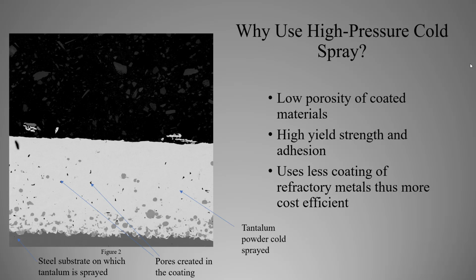The low temperature and solid state deposition associated with cold spray allows refractory materials such as tantalum to be deposited without high temperature requirements. The main aim of this method is to obtain a dense and non-porous coating. This process increases the hardness and adhesion strength of the material. Tantalum is chosen to work with high pressure cold spray process to develop thin coating and layers on the steel substrate to obtain a wear and corrosion resistant material.